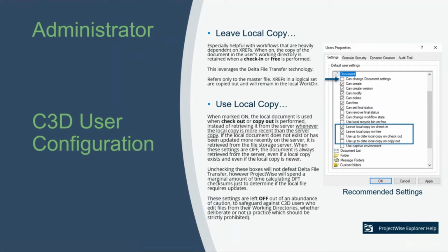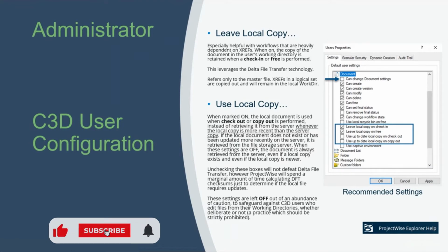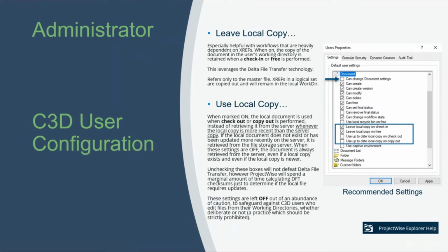I think for anybody working with XREFs, this is probably more consequential than for people who aren't, who are just updating information, possibly behind the integration. But when it comes to Civil 3D, we're establishing file relationships through the Data Shortcut project. And anything that's done without ProjectWise integration is done without the knowledge of ProjectWise. So when it eventually gets written back up to the server, there are parts of your Data Shortcut project that aren't going to work the same for the next user as they do for you if you've worked behind the integration. So we really want to encourage you to not check those last 2 boxes and keep your Data Shortcut projects from being polluted in that way.